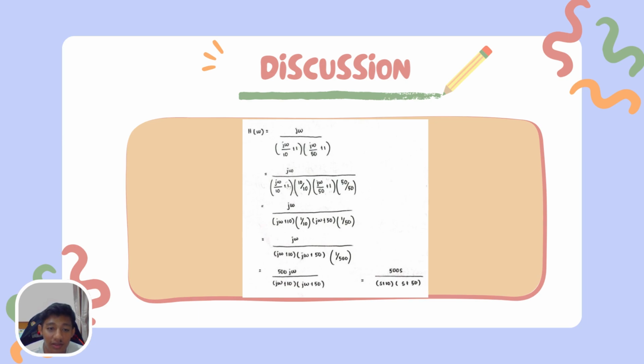We just need to rewrite it again: j omega over (j omega over 10 plus 1). To eliminate the 10 in j omega over 10, we need to multiply by 10 over 10. So when we put the 10 over 10 here, we take the 10 above and multiply it inside j omega over 10 plus 1, which eliminates the 10, giving j omega plus 10. Then we have 1 over 10 here. For j omega over 50 plus 1, we use the same method, multiplying by 50 over 50.